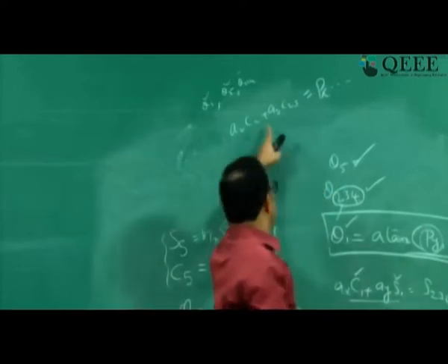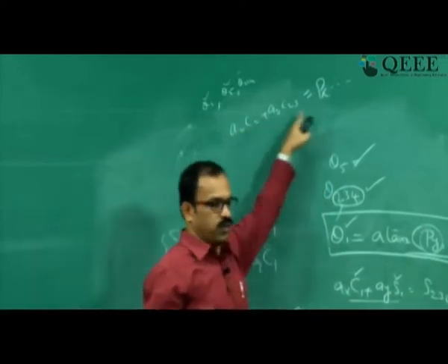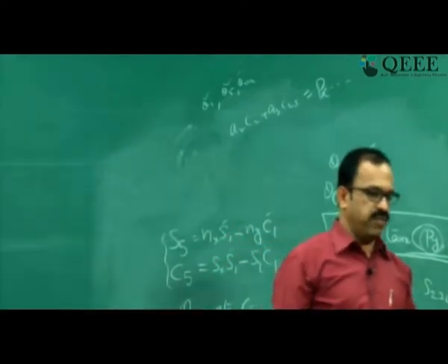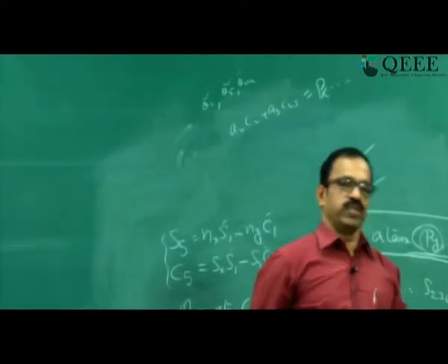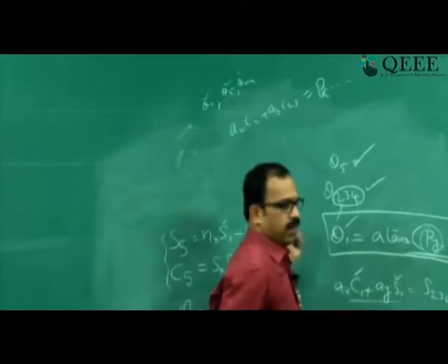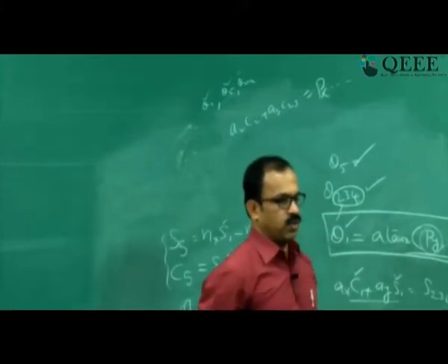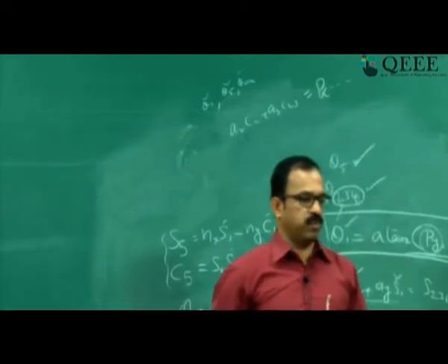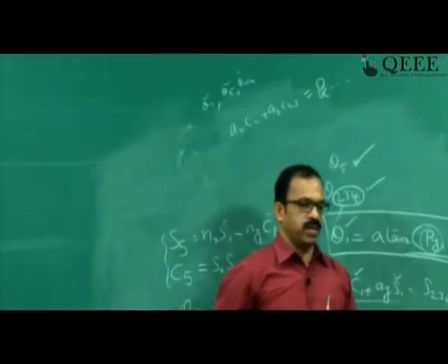So that is what we are doing in this step. A3C23 plus A2C2 is equal to Px by C1 plus D5 S234 minus A4 C234. And similarly, we will write A3 S23 plus A2 S2 equal to D1 minus A4 S234 minus D5 C234 minus Pz.